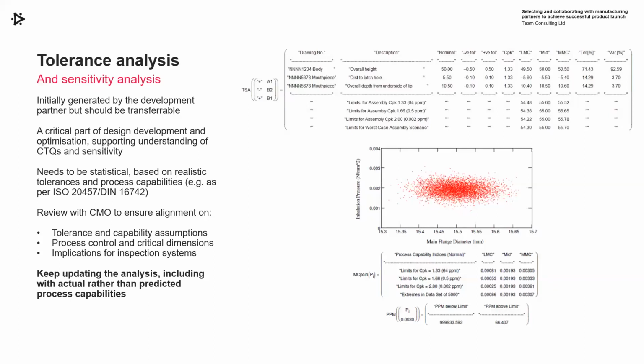In whatever system you use, this image here is based on MathCAD, which is our preferred method of doing tolerance analysis, but you could do it in Excel, you can do it in CTOL. Key thing, it should be statistical, and it should be based on realistic tolerances and process capabilities. You can base that on ISO standards, for example, those ones there for molded parts. So be realistic, apply the realistic tolerances and develop a design which will work to them. Don't apply the tolerances that you need for a system to work.